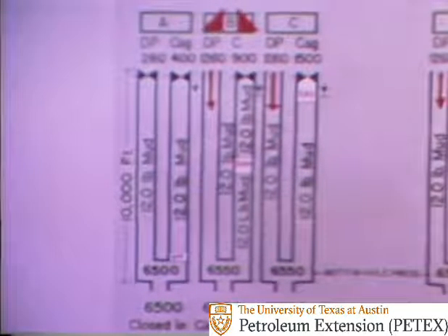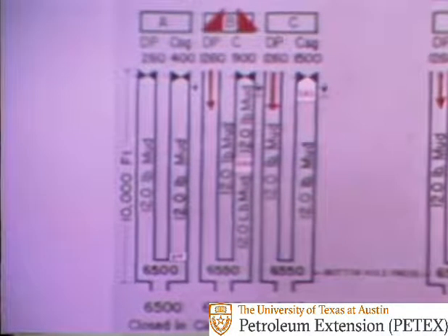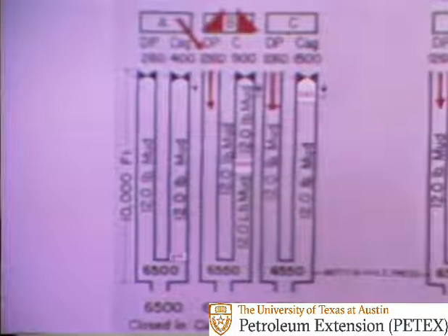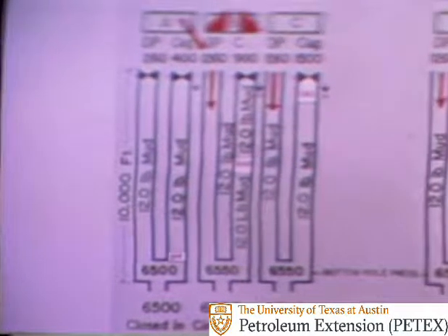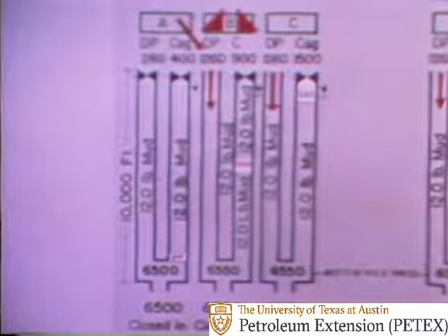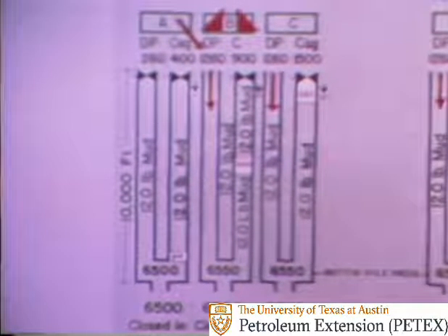When the pump is started and held at the pre-selected pumping rate to circulate out the kick, or at B, the drill pipe pressure will rise to 1,260 psi, the pre-selected 1,000 psi pump pressure, plus the 260 psi shut-in pressure, and be maintained there by adjusting the choke opening so as to hold a constant pressure on the formation.